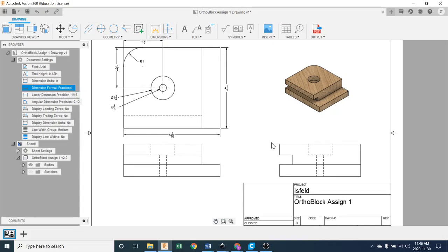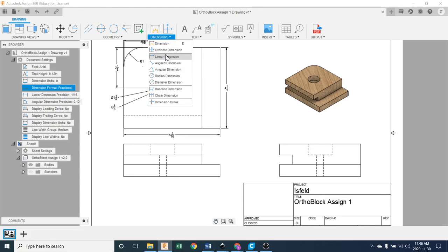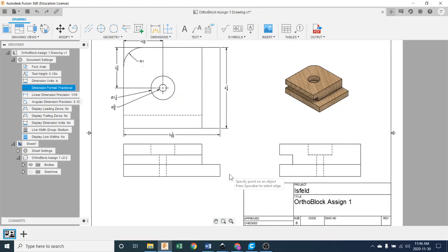So what's next? I can't show any of the elevations on this because I'm looking at a bird's eye view. So I do have to show the elevations on this drawing. So I would do my horizontal vertical, and I would go to my linear dimension, and I would show an overall dimension in height. And if I step it off one, I know I have to show these other dimensions. So I'm going to get a little crowded in here. I'm going to hit Control Z and do this differently.